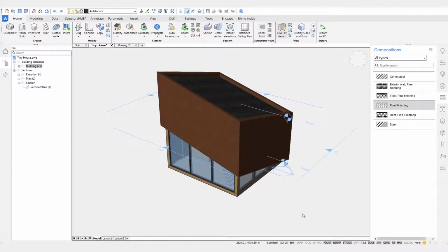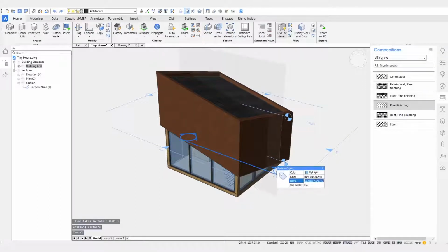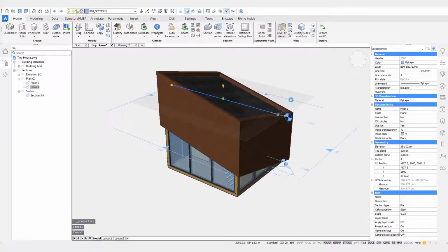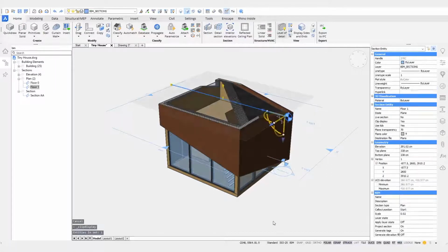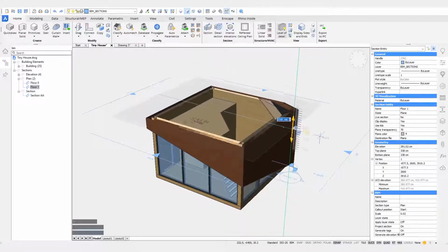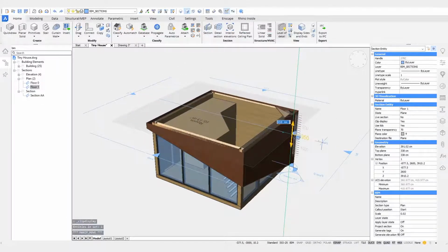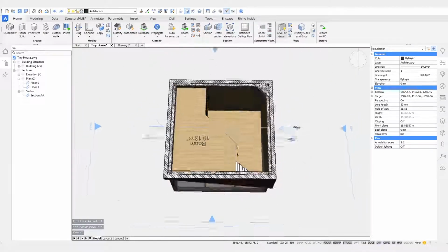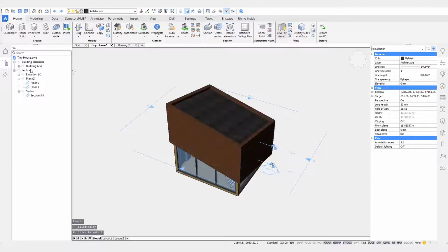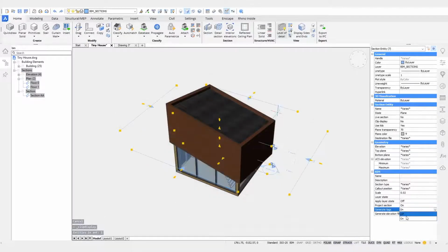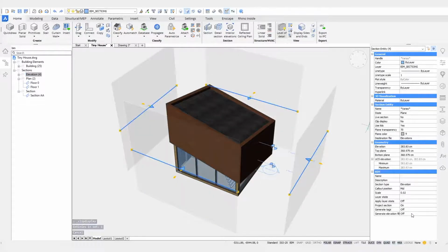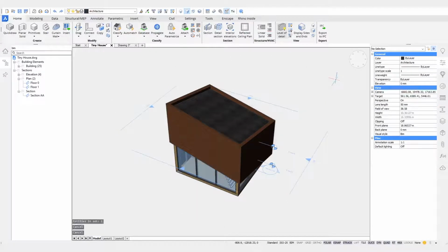It also creates spatial locations and assigns objects to these locations, so buildings and stories. It creates sections or elevations and floor sections, things like that, rooms. It also created these two floor plans, or floor plan section planes. One for the ground floor. And now I can use these section planes to generate some drawings. So I want to have some elevations, want to have some floor plans, and also this section that I've been using to section through my building. I can also use it to generate a 2D section, of course.